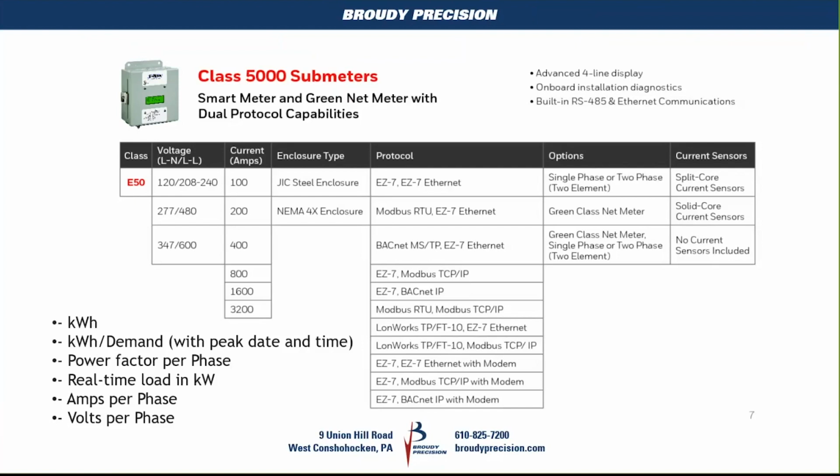And there are displays with these meters that you can walk up to and read. And so one of the things that I often bring up with customers that are purchasing meters from us, this is good information for analytics, but it's also good for control and demand limiting and some of the other strategies we're going to talk about. But when you compare what the building's utility meter is reading and what the building is getting charged with, and compare it to one of the meters that is installed slightly upstream, they may not match.